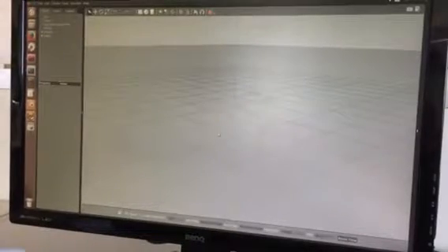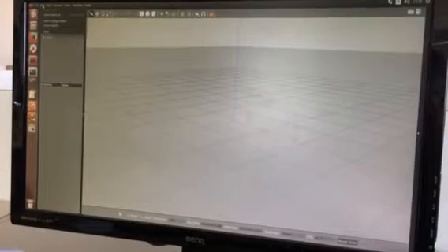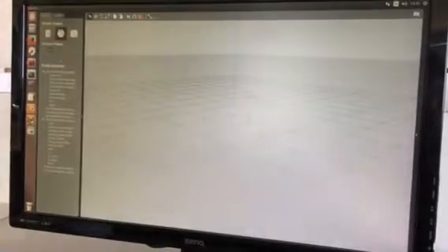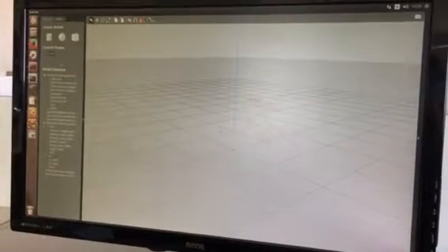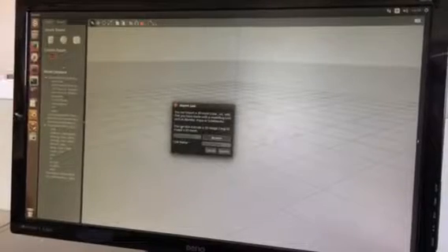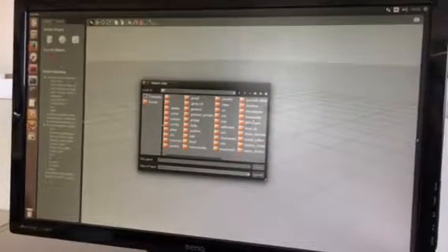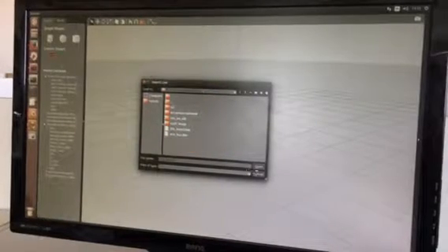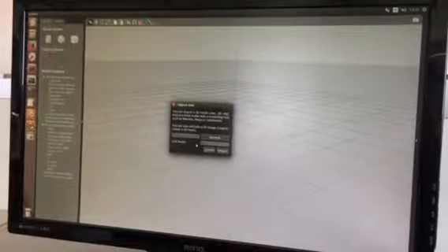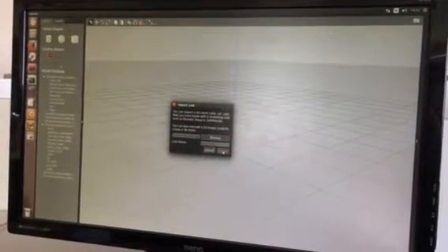So this launches an empty Gazebo for you. You go in here, I think it's in Edit, and then Model Editor. Once you open the Model Editor, you can add custom shapes here. You click add, and then you browse for your Collada file. My Collada file is here, nice box. And then you put the name here, nice box. This will be the name of the model in Gazebo also.